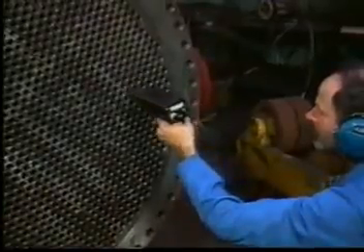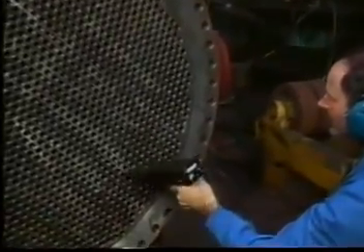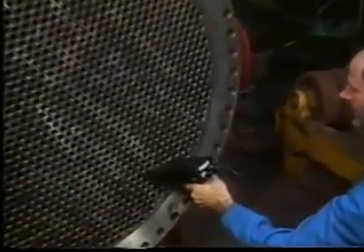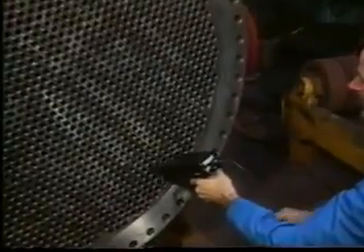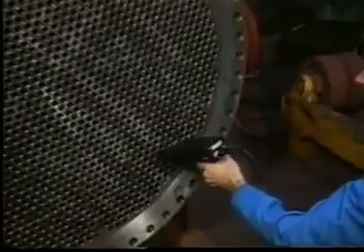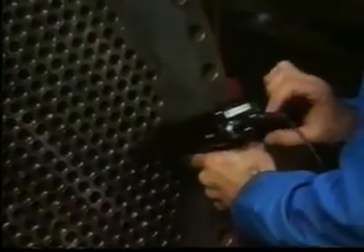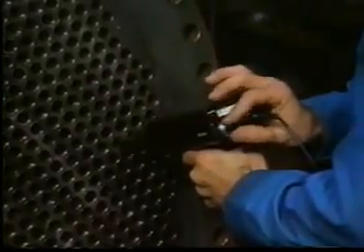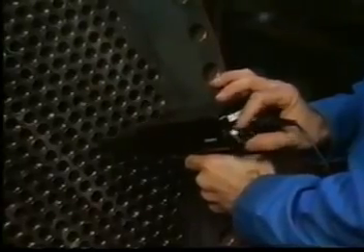As we move away from these areas, sound intensities will change, producing new zones. When you see a change in intensity levels and recognize there is a new area, readjust the sensitivity to read 50 on the meter again and continue testing until you enter another zone.